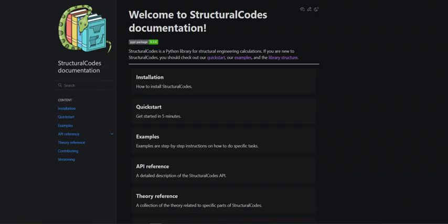So instead we could do geometry equals a rectangular geometry. So create an instance of the rectangular geometry class. Here we simply specify a width and a height and the material. So let's now see what happens if we do it like that. I will click save, and let's see if it runs all of it.